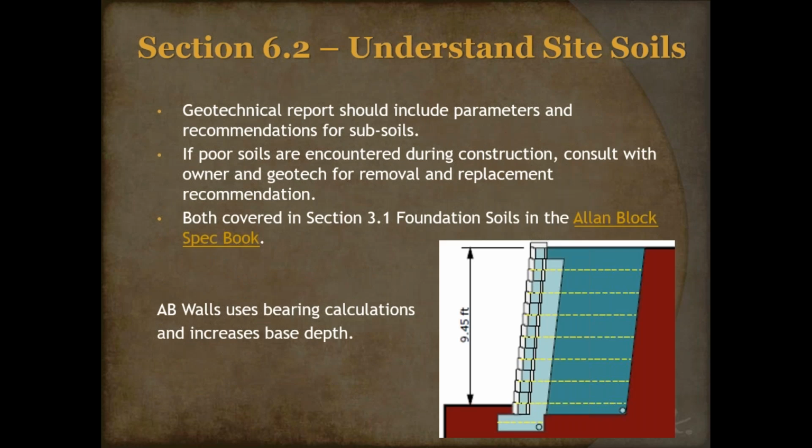Okay. 6.2. This is understanding your site soils. Plain and simple, we just need that geotechnical engineer involved. We need that on-site soil, making sure we've got material that's been covered. And this is really kind of getting into more of the subsoils more than even the backfill. Subsoils, to me, is probably where the most assumptions are made, where we've got a better idea what the backfill material is going to be, but then we just scratch the surface because we don't need a concrete footing here. We scratch the surface and then we just start building a wall. Meanwhile, we could have been building on some fill, a marsh area, some wetlands. We've even seen guys build on cars and trenches and stuff like that. So understanding what's below grade is so important.